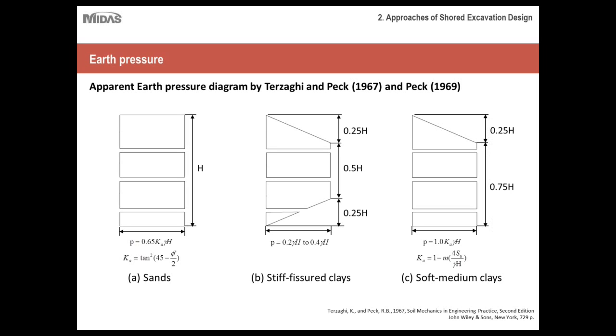the soil strata. So two things we can observe from here, that soil pressure definitely varies depending upon the soil type you are using, and it definitely varies with the depth of the excavation. And if the depth of the excavation is very deep, then these variations are different from the realistic behavior. We'll talk about that in a short while.